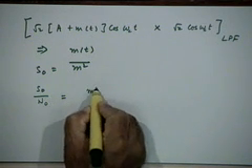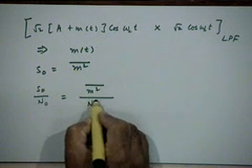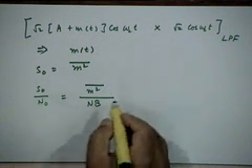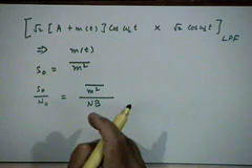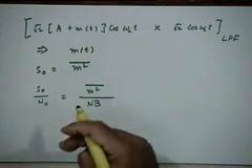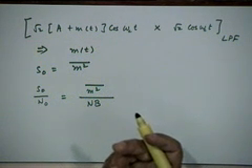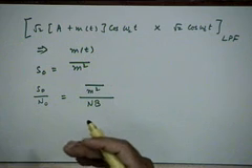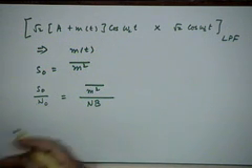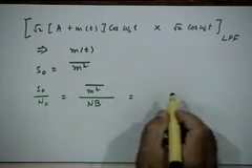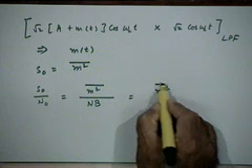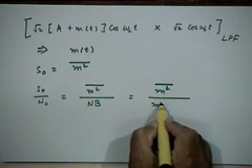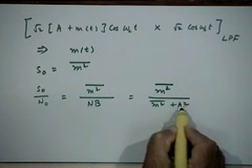It is m square bar upon NB, and now I must express it in terms of signal to noise ratio of the input, because that is our benchmark, right? Our benchmark is in terms of SI by NB. Suppose I were to do that, I can rewrite this as m square bar upon m square bar plus A square, which is your SI.